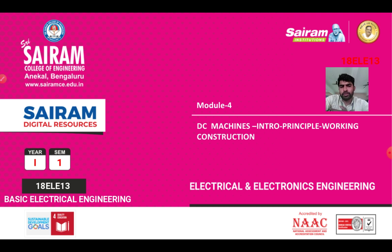First I'll see the principle, the DC machine principle and the DC motor principle. We have three major principles. At least you should remember any one. What about Faraday's laws of electromagnetic induction? Faraday's first law: when a conductor cuts the magnetic field, EMF is induced. The magnetic field is constant, the conductors are rotating, the conductor cuts the magnetic field, EMF is induced.